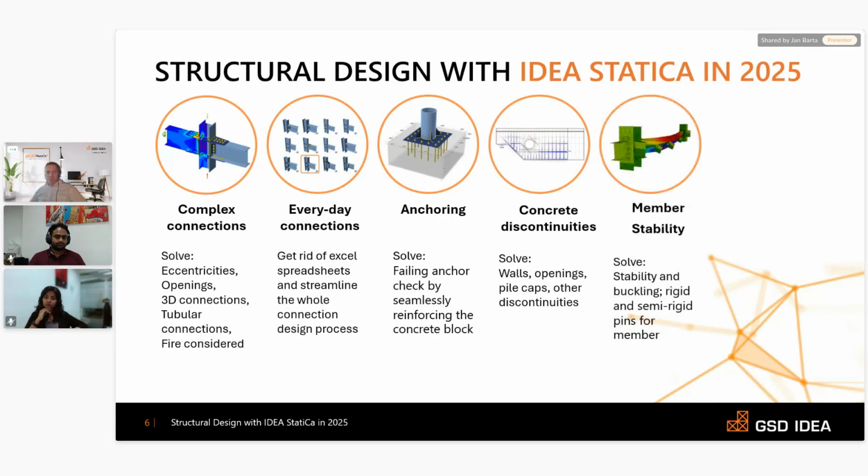Member stability is another very time consuming issue, and also very difficult to calculate without Idea Statica, since the global FEA typically covers the global buckling, while the local buckling needs to be covered in some other software. So one of those software can be Idea Statica, and again, keep you on the safe side and save hours.